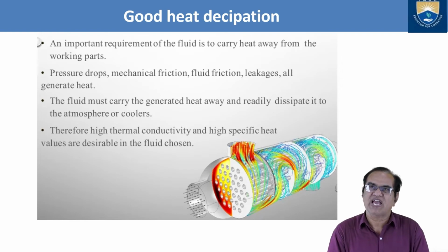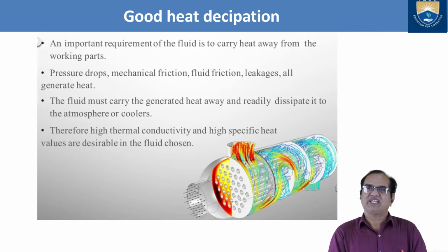So the fluid must carry the generated heat away and readily dissipate it to the atmosphere or cooler. Therefore, high thermal conductivity and high specific heat value are desirable in the fluid chosen.